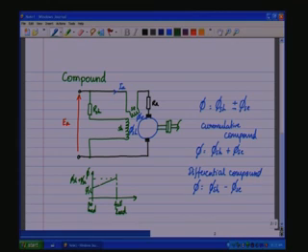So, as the flux increases, you saw that the back EMF is connected across the armature winding, and if the back EMF is constant for a given speed, then as the flux increases, the speed will reduce. Which means that as the load is changed from no load to full load, flux is increasing and the speed will reduce. And in the case of the differentially compound motor, as the load is increased from no load to full load,